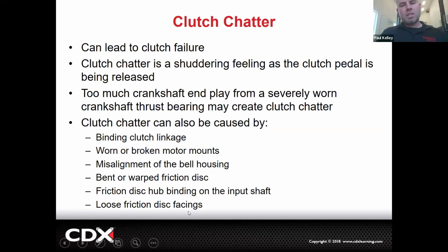The most common that I see would be rear main seal leaking and soaking part of the disc in oil, but not another part of the disc. So it'd be a slip stick condition, or flywheel runout. Those are the two most common.